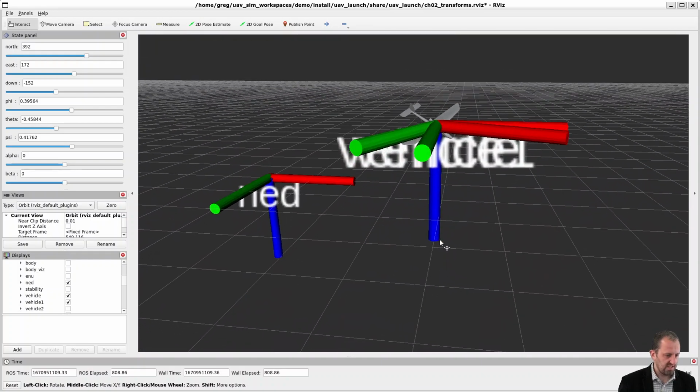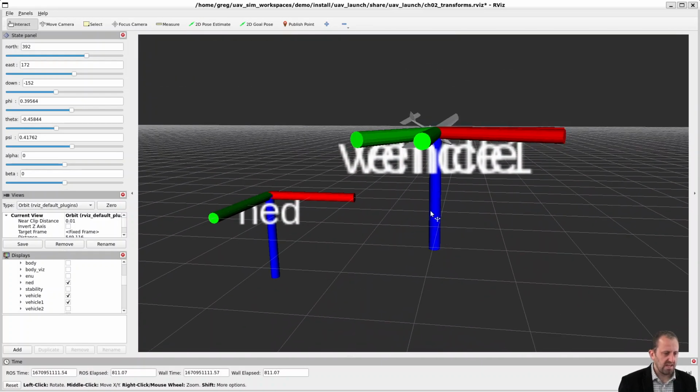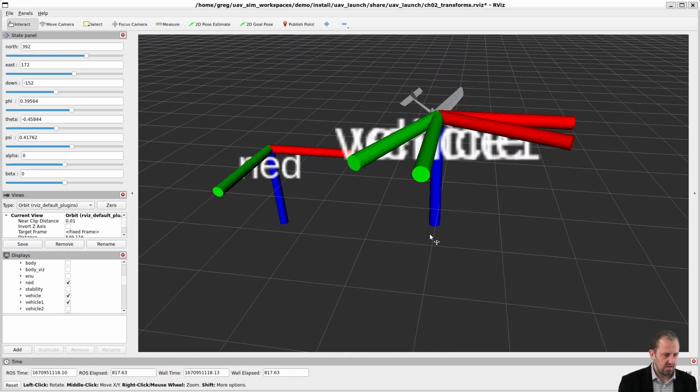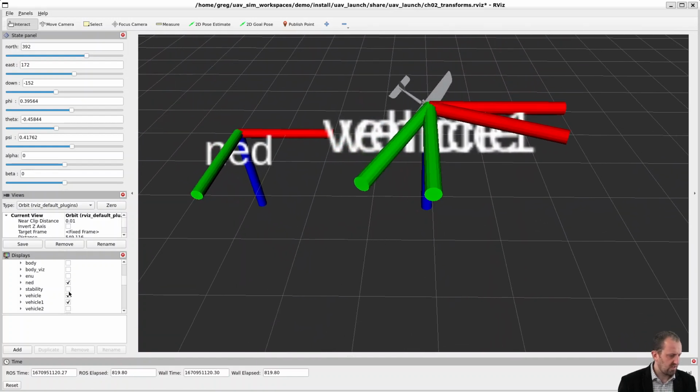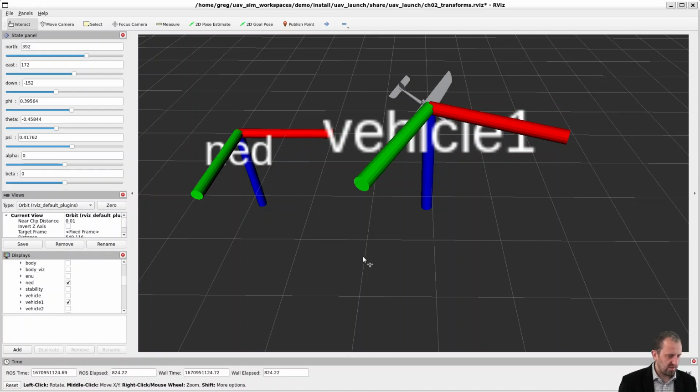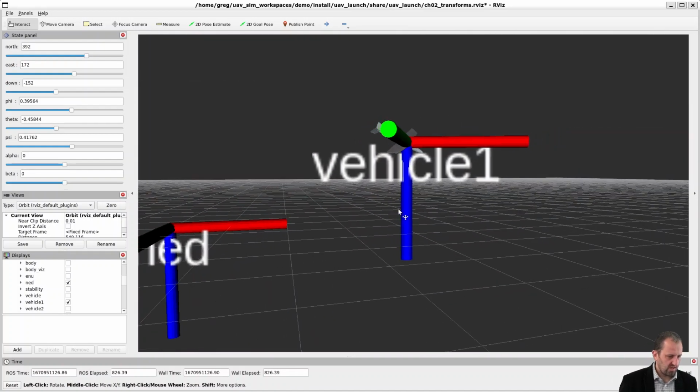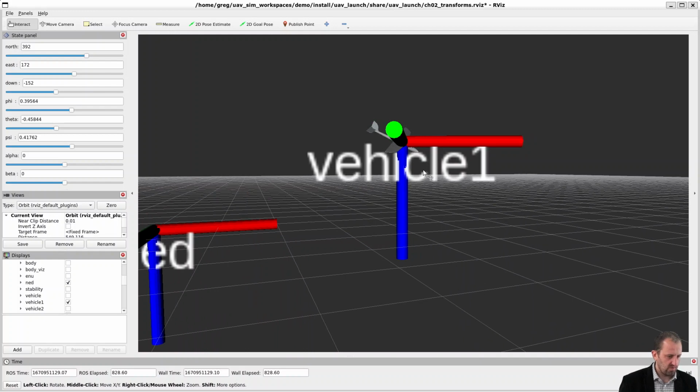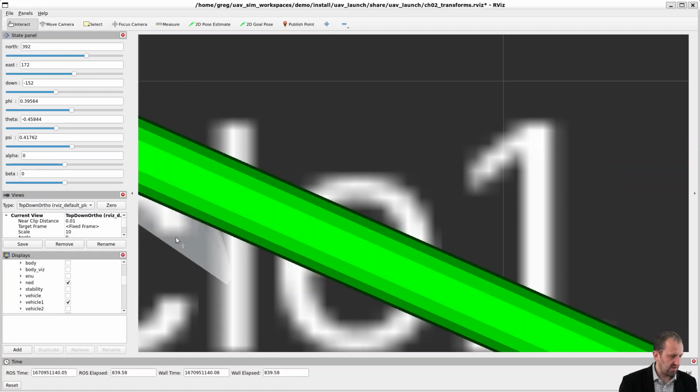But what I want you to see is that we've done a rotation about our z-axis. So the z-axis is the same in both the vehicle and the vehicle 1 frame. Now we can stop looking at our vehicle frame and look at our vehicle 1 frame. What you're going to want to see is that the nose, if we projected it up into the northeast plane, is running parallel with this red vector. The easiest way to see that is to do a top-down view.